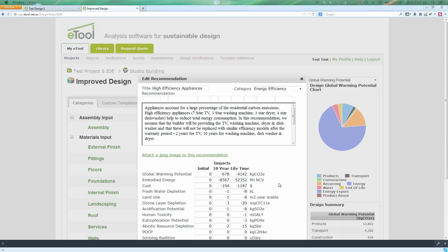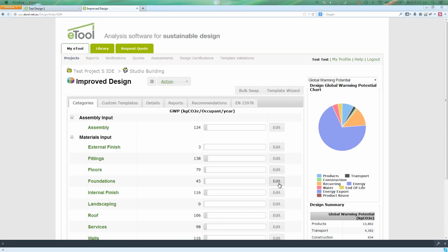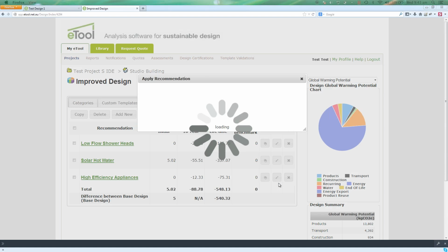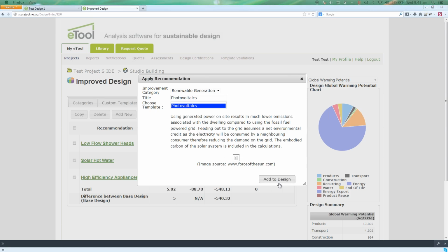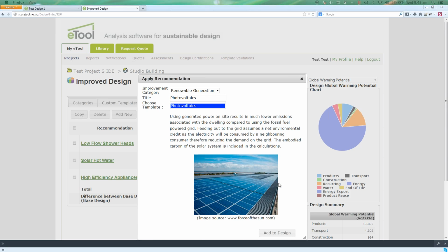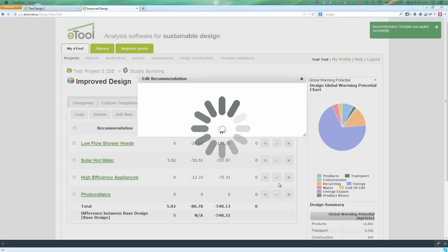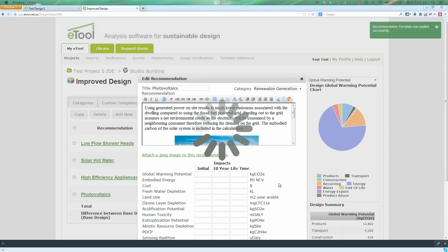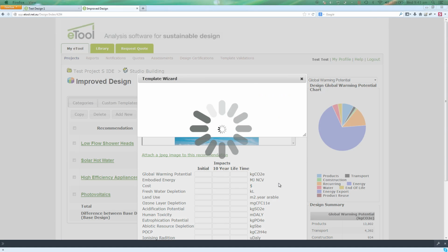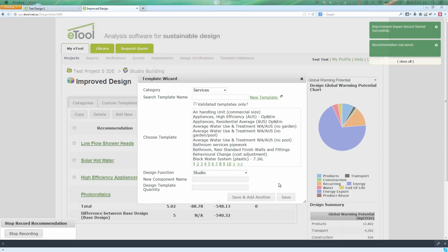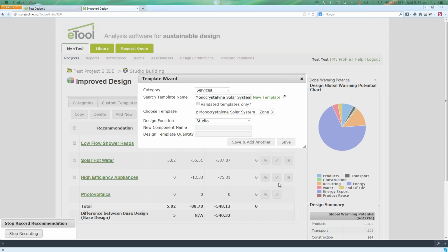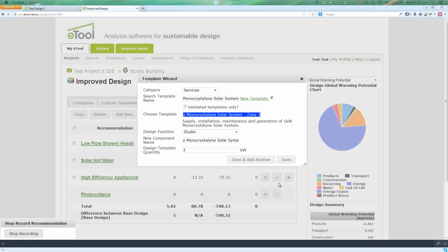So the other thing, with all the templates in eTool, what we're really talking about is how an average occupant would use this building, not necessarily a good occupant or a bad occupant, but an average occupant. So it's almost like if you built this thing 1,000 times, and you averaged all the energy use over those 1,000 buildings, then we think that these figures would be quite correct. So obviously on a case-by-case basis, there's going to be pretty big standard deviation due to occupant behaviour. And I guess once more, if you're on a really low carbon grid, then the materials would be the dominant impact. So effectively your assessment would probably be more robust in terms of overall impacts if you're on a low carbon grid, because everything would be wrapped up in materials where there's actually more surety about what's going into the building and being used.